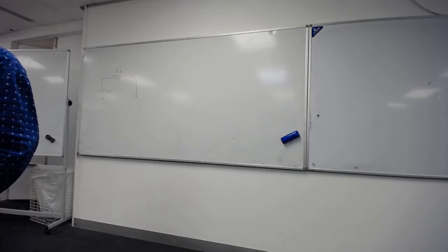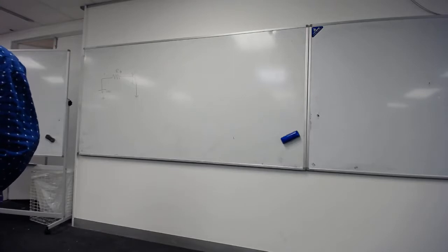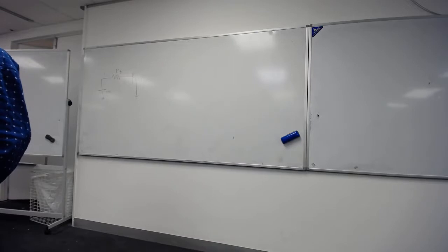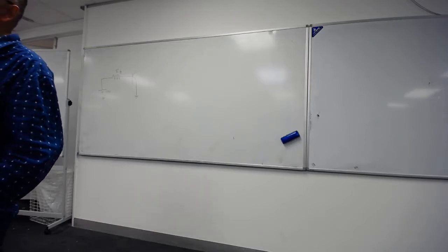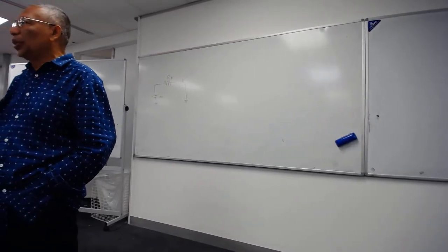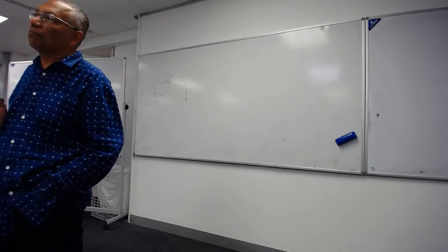Whereas the GM is not dependent on the fabrication. GM is dependent on the bias current that flows through it, which depends on the circuit that you design, because it depends on ICQ. That is the bias current that you allow to flow because of the way you bias the circuit. So GM is dependent on the circuit. Beta is not dependent on the circuit. You can create a circuit to measure the beta, but beta will never change. Okay?